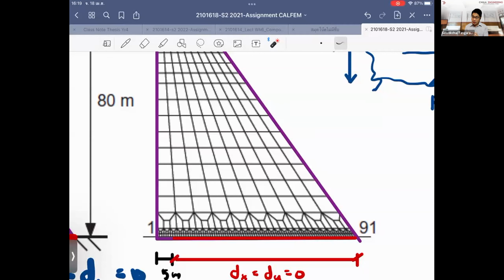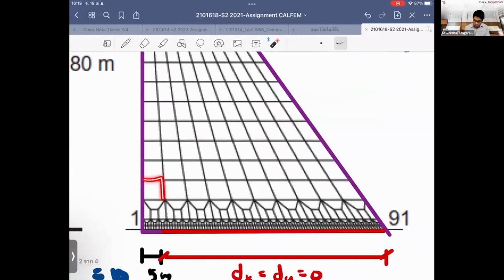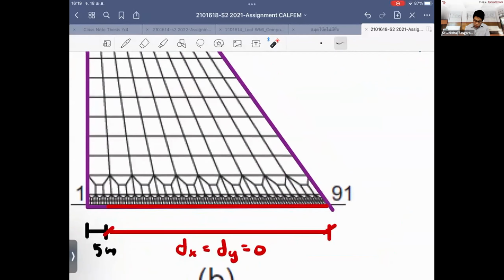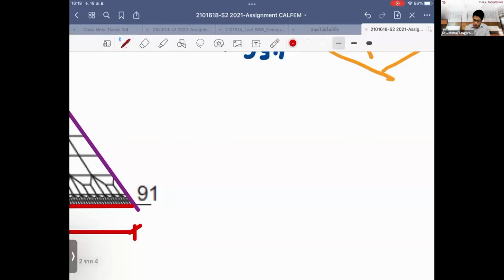The more mesh you have, the more accurate the stress you can obtain. If you use the uniform one, we call this uniform refinement, so you would need so many elements in the model, and that is very painful. So what I suggest is that you should use some type of transformation. The nice thing about this type of mesh pattern is as follows. Listen to me first.